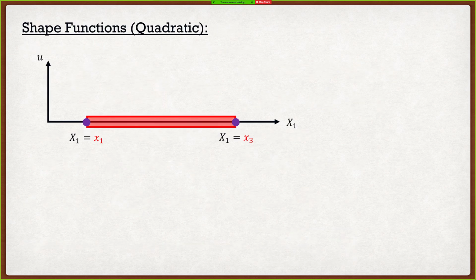So if we were to go back to our exact same bar here, we say, all right, I know that I have 2 nodal displacements, u1 and u2. But what I'm going to do in this element right here is I'm actually going to introduce a 3rd node. Now this 3rd node is going to be at the midspan of our element. So this is where those of you in 660 might start saying, Clayton, I hate you now. Because 660 was nice and easy.